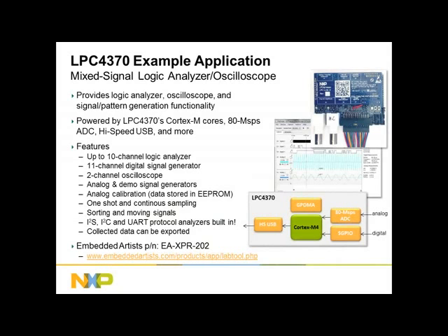Embedded Artist is a third party that we work with, and they came up with a very clever use of the 4370. Basically, they've created a logic analyzer, oscilloscope and signal generator using this one-chip solution, if you will. They've got a 10-channel logic analyzer and a 2-channel oscilloscope taking advantage of the ADC and the serial GPIO inputs. The signal generator actually uses our very low-end Cortex-M0+ LPC4370, which is also on the board. But in terms of what the 4370 is doing, it's the logic analyzer, oscilloscope and the connection back to the PC.